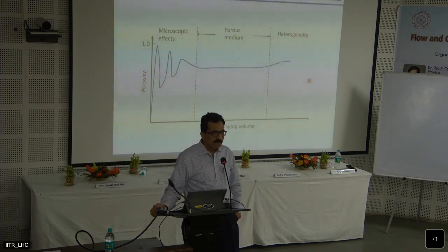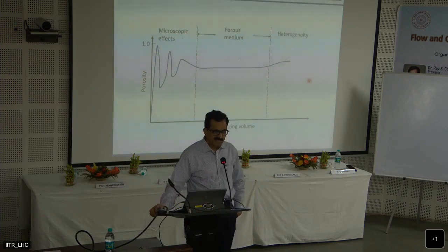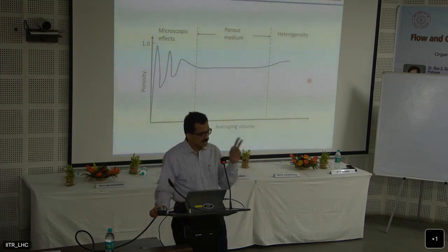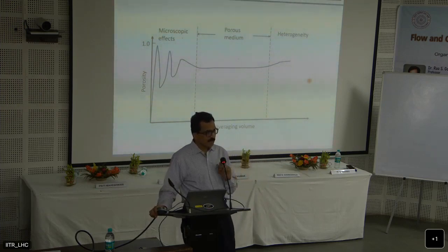The problem is that in the laboratory we actually do not measure pore sizes, or not typically. What we measure are particle sizes, and we try to infer the pore size distribution from the particle size distribution. They are not the same. That transformation is not automatic.